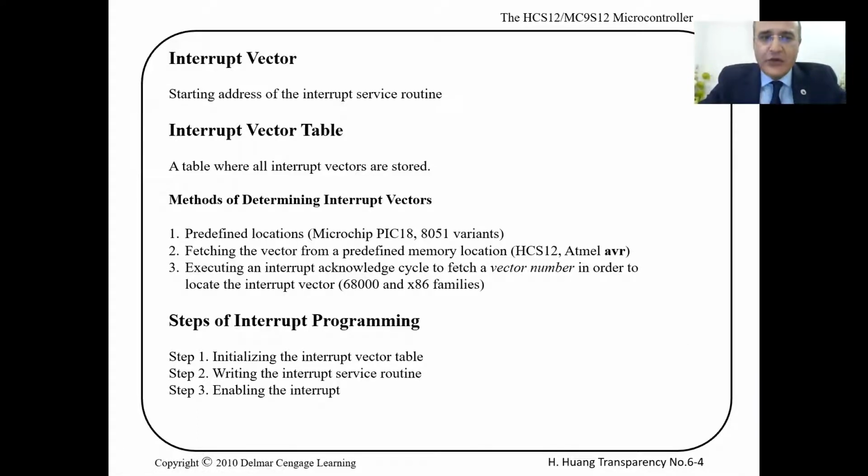So an interrupt is something that is supported by hardware that interrupts the normal program flow, taking the program counter to a piece of code out of sequence, asynchronous. We don't know when to execute something in response to an event. The event can be a hardware or a software event, but it has to be supported by the hardware to force the program counter to go to the new place and to save the CPU status to be able to go back to normal execution when the interrupt source disappears.